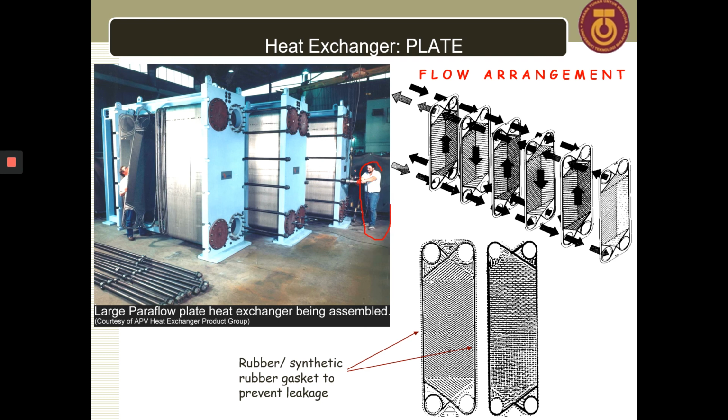And what is the application for a heat exchanger of this configuration? So please find it. Or maybe I just tell you, mostly the plate heat exchanger is used for heat transfer at a small temperature difference. That means products that are very sensitive to heat, like drugs, pharmaceutical products or cosmetic products, are very sensitive to temperature, right?